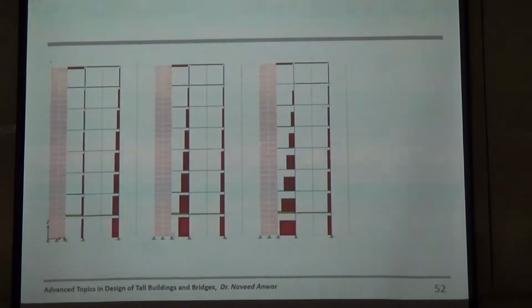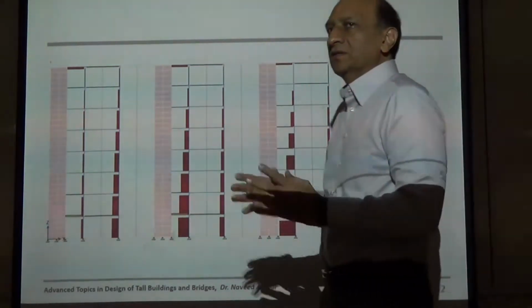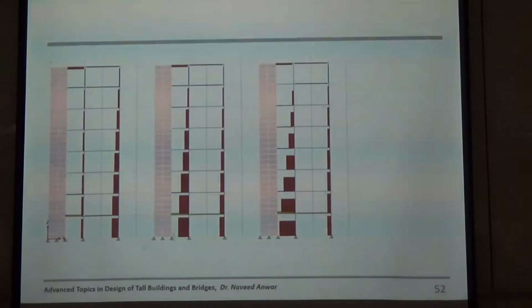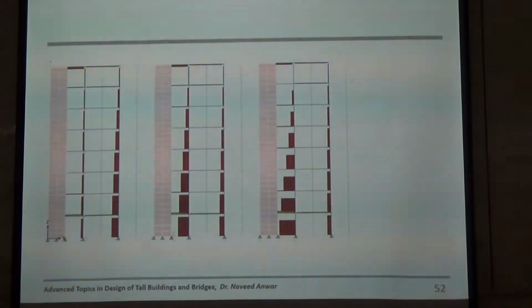That is where the shear wall and frame act together and increase the strength a lot, because the axial stiffness or axial reaction in the column is added to the lateral resistance, which otherwise is not present. Understand? That is the key that you must remember. Whenever you can convert the bending action and resist it by axial forces, that is the best way, and we are always trying to find a way to do that in tall buildings. Tube is the same thing. Tube converts the bending into axial stresses in the wall.